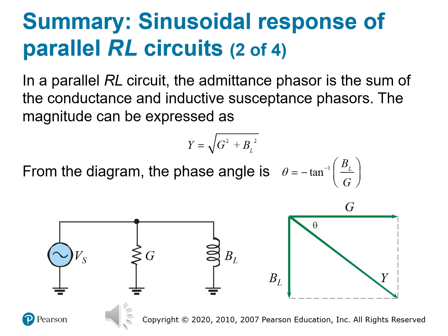In phasor form, G is plotted on the real axis, the horizontal axis, and B sub L is plotted on the negative imaginary axis because inductors cause current lag. The diagonal is the total admittance, denoted by Y. And yes, this forms a right triangle, just like with impedance, but with the axis inverted. So you can use a formula for magnitude: Y is equal to the square root of G squared plus B sub L squared, that whole thing square rooted.